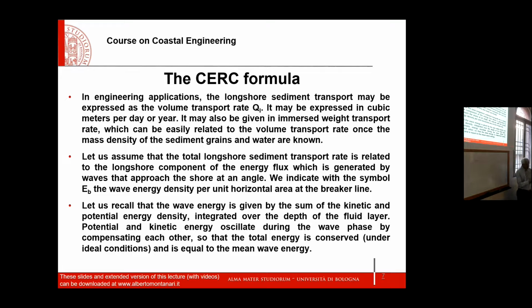So I take a finite difference approach. I think you are a bit familiar with numerical modeling. Numerical modeling means that when you have a system that is very heterogeneous and cannot be described analytically, we solve piece by piece by taking a finite difference approach. So I have typically differential equations which apply to each delta. This numerical modeling involves an approximation, and you can see it here, because of course the resulting shape of the beach cannot be made by steps. So what will happen here, actually, in reality, will be something like this. Okay? But the effect of the numerical approximation gives a representation by steps.